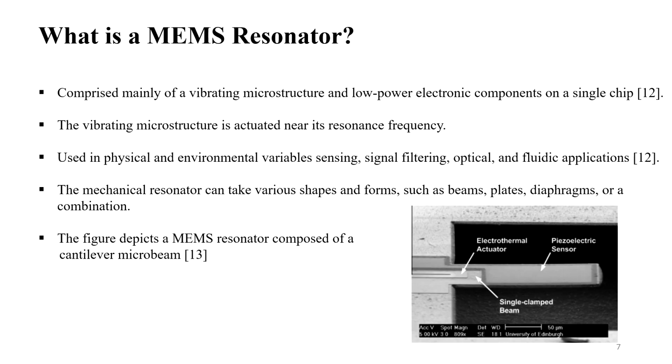MEMS resonators typically consist of a vibrating microstructure actuated near its natural frequency. They are used in sensing, frequency filtering, and signal processing. The vibrating microstructure can take various shapes and forms, such as beams, plates, diaphragms, or a combination. However, we will be focusing on the beam plate configuration in this presentation.